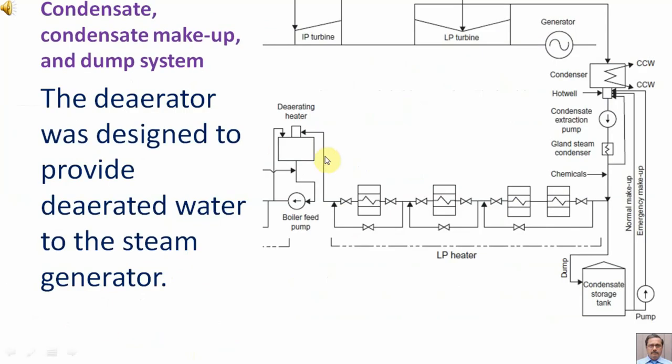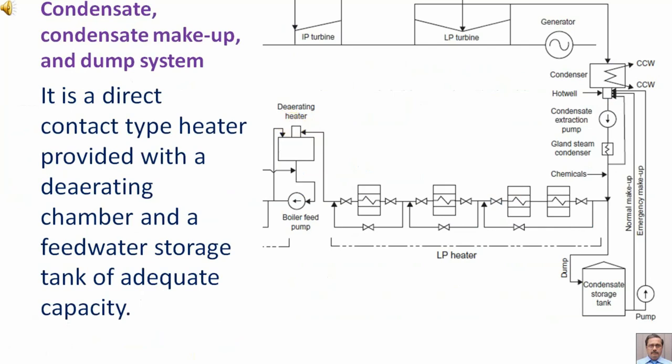The deaerator is designed to provide deaerated water to the steam generator. It is a direct contact type heater provided with a deaerating chamber and a feed water storage tank of adequate capacity.